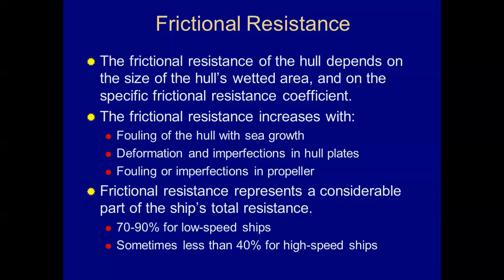So frictional resistance increases with fouling of the hull with sea growth, deformation, and imperfections in the hull plates. You're hitting the dock, the tugs are pushing on you, all those dents on the hull. Do they slow you down? You bet. Fouling or imperfections in the propeller, and by the way, having sea growth on the propeller. There are services that will come out, and while the ship's in the water, will clean both the hull and the propeller for you.